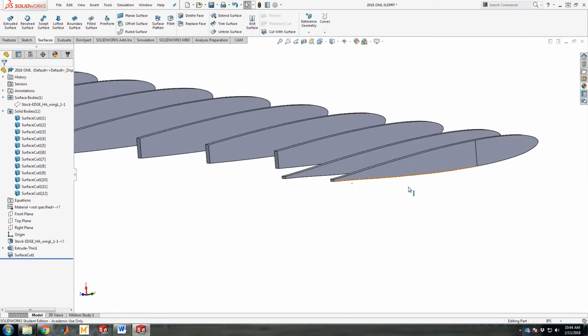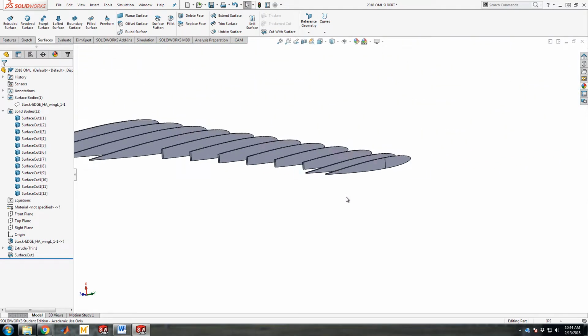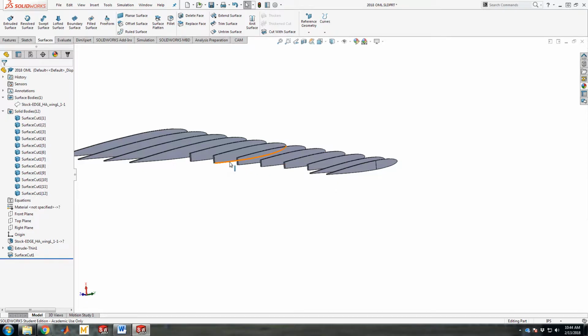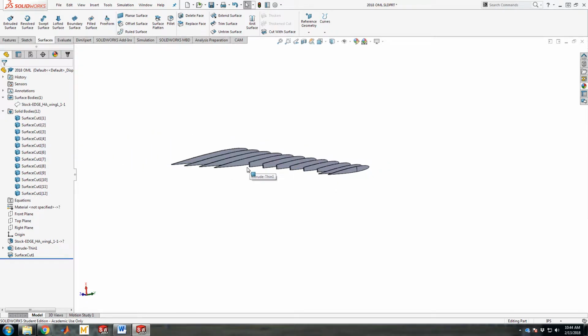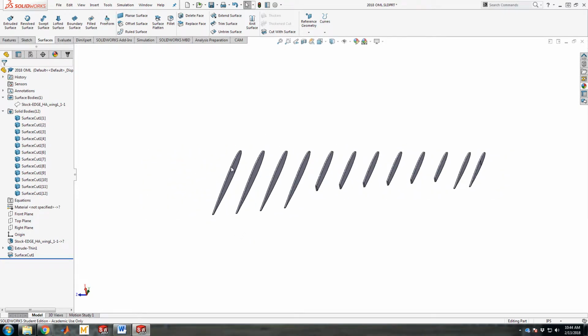In circumstances where you had extreme contraction, and you actually wanted a rib to include a contour, you would have to CNC machine that rib out, probably with multiple vertical passes, so that would put that contour inside the rib structure, and it works. I've done that on at least one UAV. It just takes a little bit more time. Okay, so those are ribs.